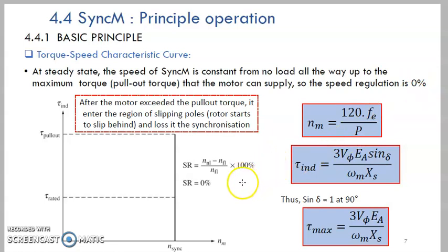because it's not like your induction motor, where the speed will follow the frequency rotation. For synchronous, the speed will be at the same frequency as your system frequency. So speed is 120 times frequency divided by the number of poles. The lower the number of poles, minimum is 2, the higher the speed. If you put in more poles, the speed will reduce.